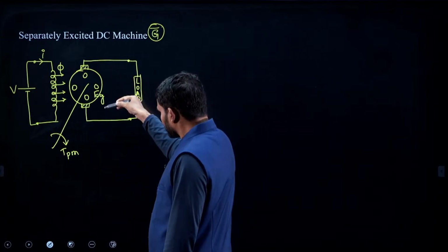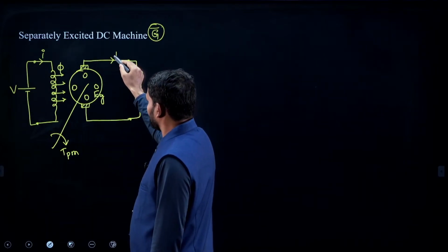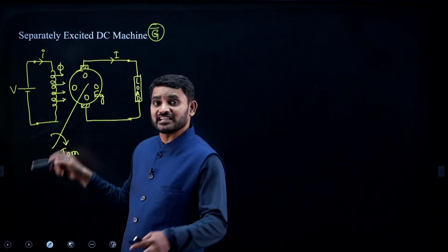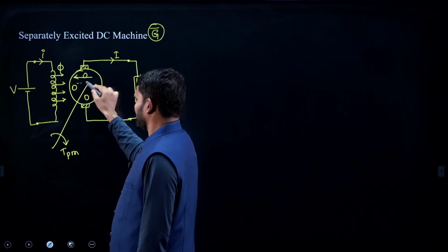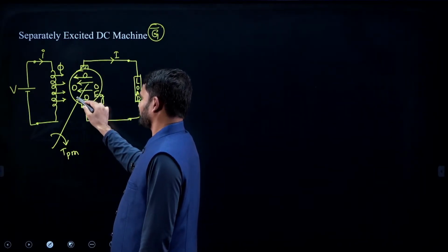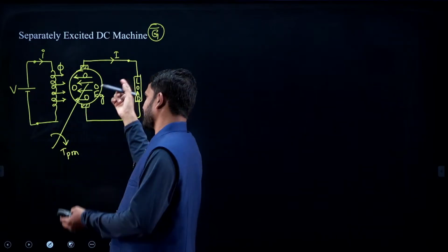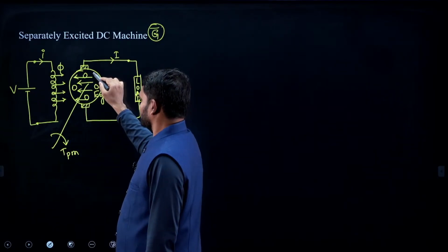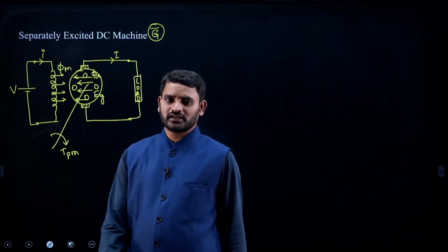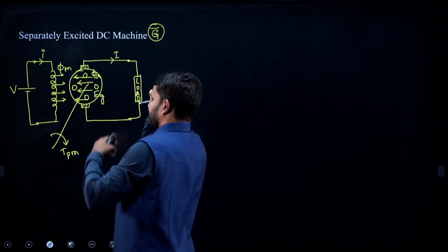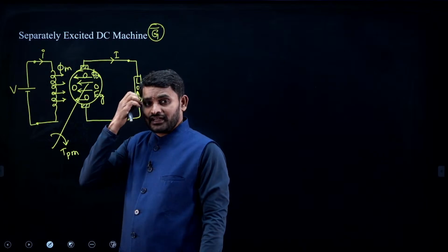So now whenever you close the circuit, EMF will drive the current, and that current will set up a flux. We call it as armature flux. Maybe quite opposite, maybe inclined, based on the current magnitude and those things. So let me take up this armature flux, and this is main field flux. Now the interaction of these two flux lines will create a torque or not?